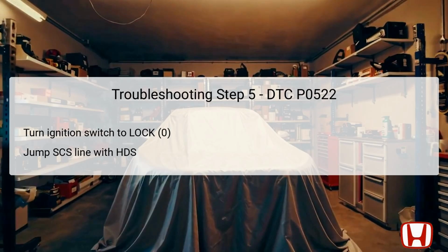After locking the ignition, you will need to jump the SCS single circuit selector line using the Honda Diagnostic System, HDS. The SCS line is crucial for performing specific tests and ensuring the correct functionality of the ECU, engine control unit. By jumping this line, you can set up the diagnostic system to focus on resolving the fault associated with the DTC. This step is crucial for confirming the operational status of the ECM and helps isolate faults without interference